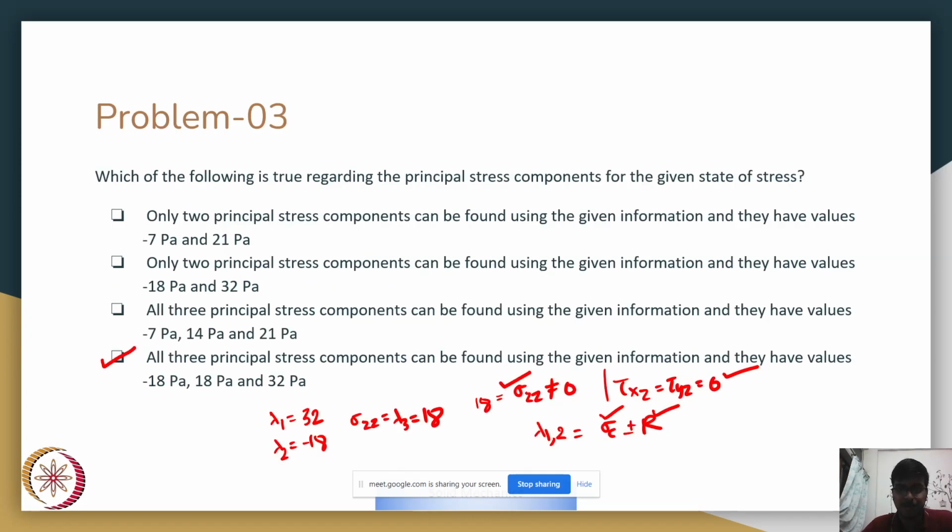So as you can see from this question, if the condition for Mohr circle is satisfied, you not only know the principal stress components, but you also know their directions as well. So everything is in a sense known. But if in general this is not aligned and you want to calculate what the principal stresses and the principal plane normals are, then you have to solve this eigenvalue equation. So this is a cubic equation. Mohr circle essentially helps us to reduce this to a quadratic.